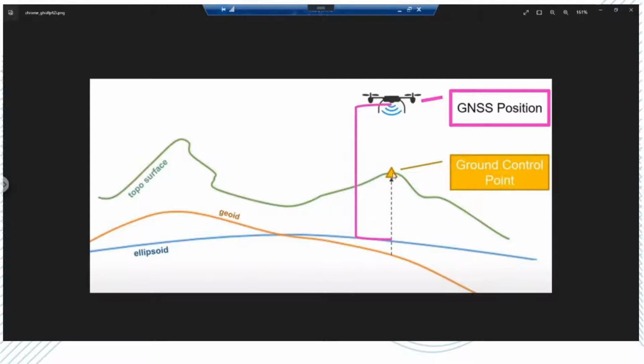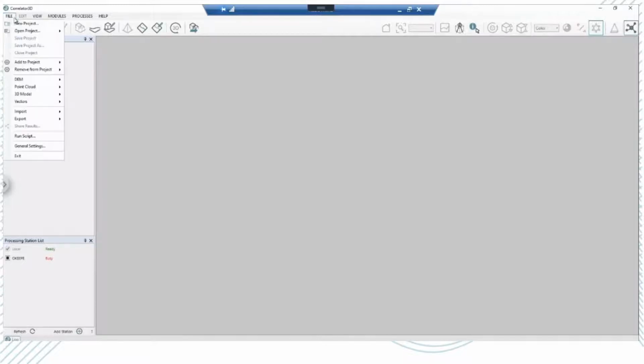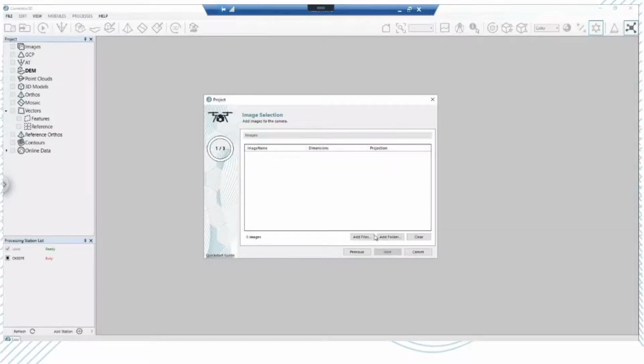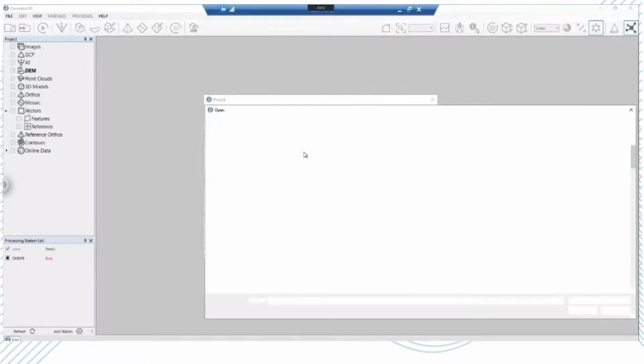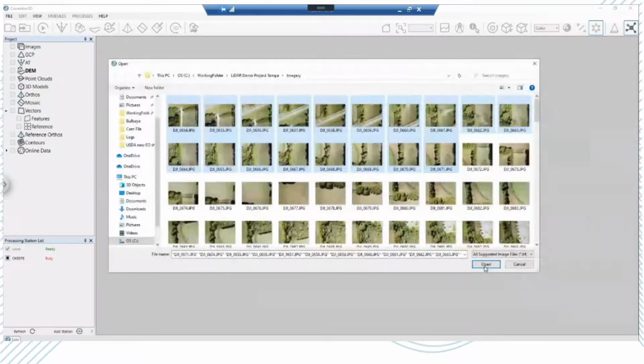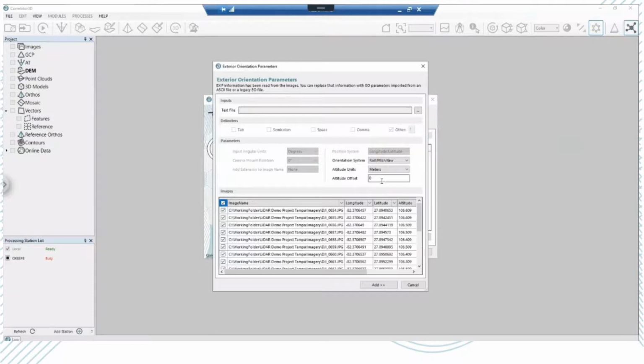Let's go ahead and open up the project. And let's go through the setup. We will open a new project, import a camera, import a couple of files here just to get through. And this is the place where you would input your altitude offset. So let's say we went through this process. We opened up that NGS link. We imported lat longs. We got an offset of 20. We would input that value in this set and hit continue.